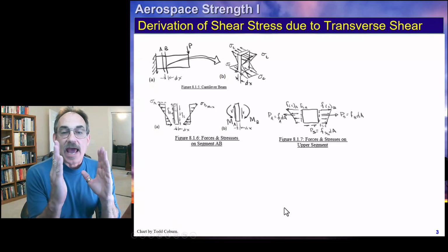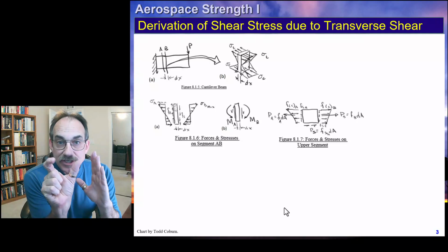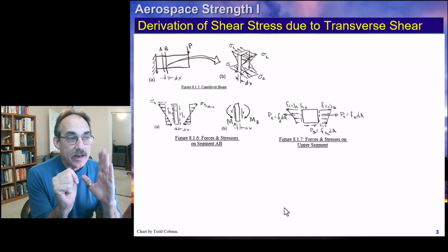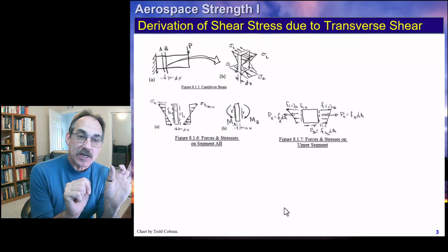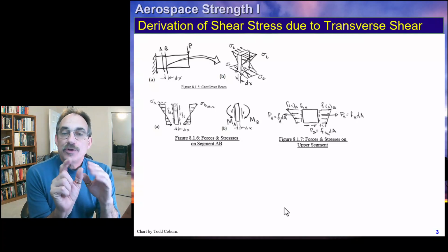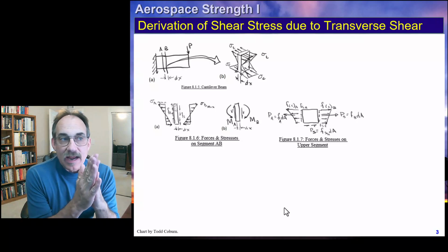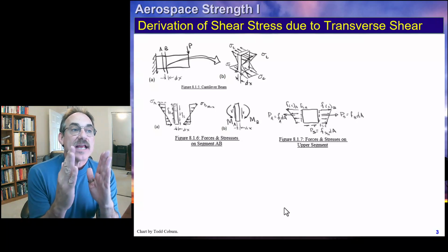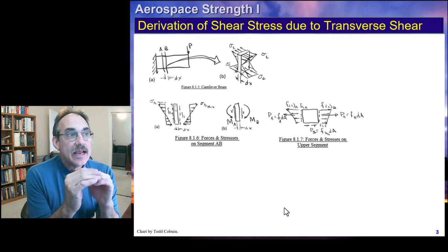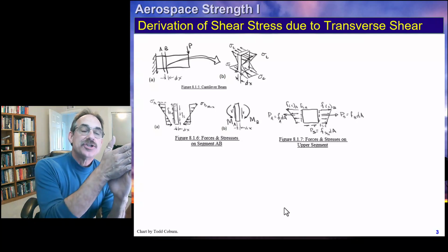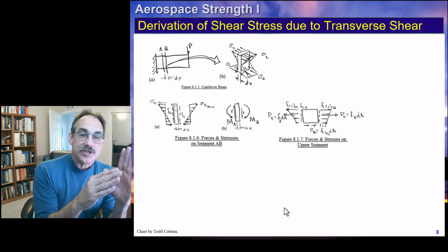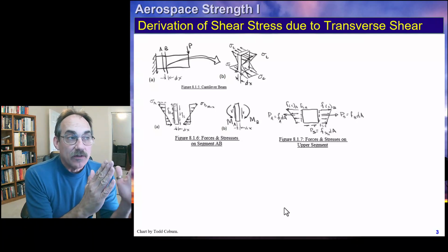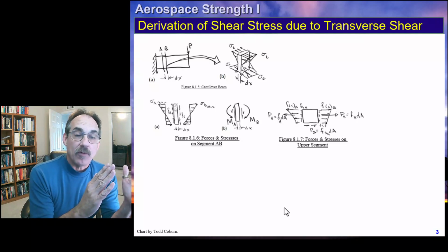Okay, so what we see here is, on the right side, we had a stress distribution going from some max stress to some lower stress, depending on where we cut it. On the left side, we have a stress distribution going from some max stress to some lower distribution. Those stresses, if we multiply them by the area of that upper piece, would give us the force acting on the rightmost face. If we integrate the stress across there, we have a uniform stress and a gradient stress. If we did that on the left side, we have some equivalent force.